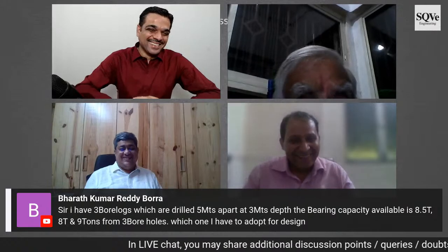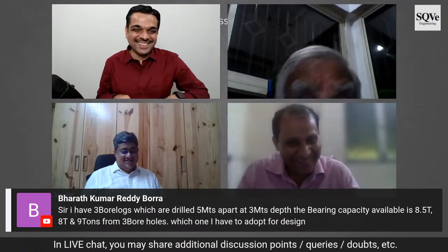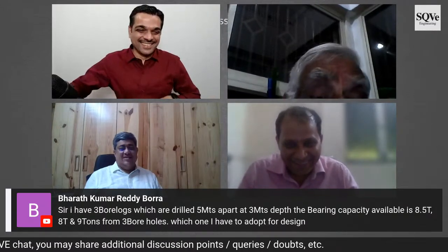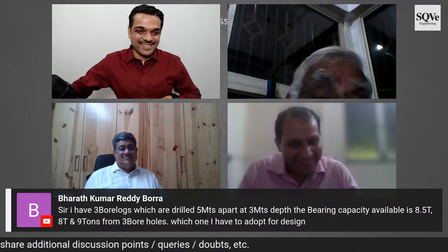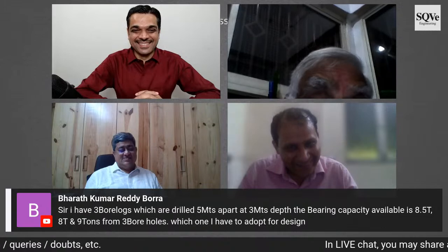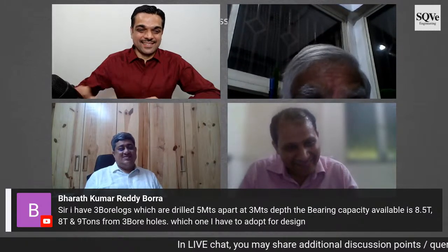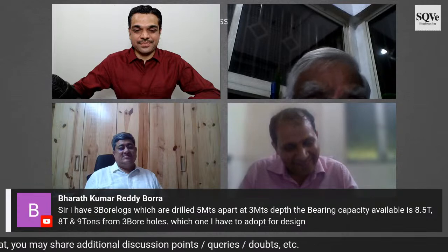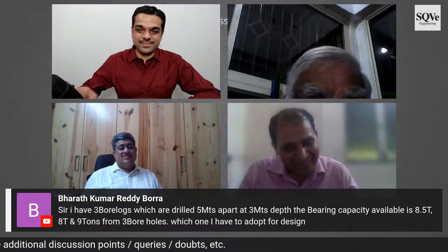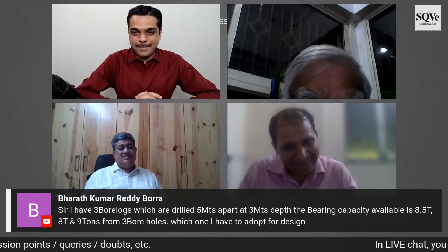So what Sandeep said is right. Even in the soil on the site, I should stand on one foot. When I stand on one foot, I generate 3 tons per square meter pressure. What is the dent that you get? Can you see it with your eyes? In a good soil, you don't. In a slightly medium or a soft clay, you might see 1 or 2 or 3 mm.